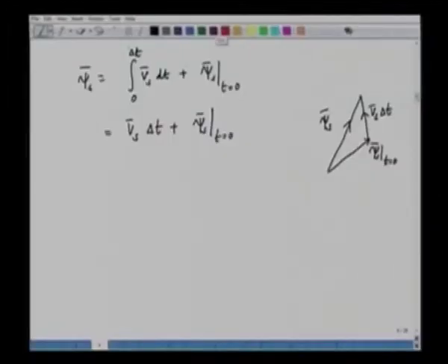So, it means if you want to control the stator flux vector, you have to apply a suitable voltage vector Vs. This Vs can be in various directions, depending upon which voltage vectors we are choosing. It can be one of the 8 voltage vectors, and 6 are non-zero voltage vectors. Accordingly, suppose this is my Vs into delta t. So, the resultant of this would be somewhere here. So, instead of this flux, I will have this flux.